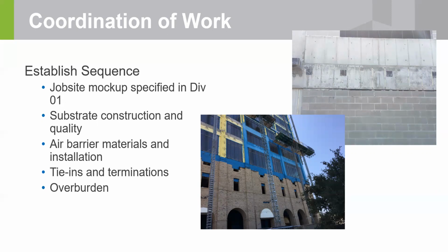The other challenge is looking at those window openings. Sealing that window direct to that membrane was much easier to do if it was done with the windows on before the brick veneer. But for practical reasons, they don't want to do that, because the mason trade has wet mortar and guys handling bricks. They're afraid of getting mortar on the windows or breaking them. So they want to get the bricks up first. But I'll show you later in the presentation, this posed a considerable difficulty.